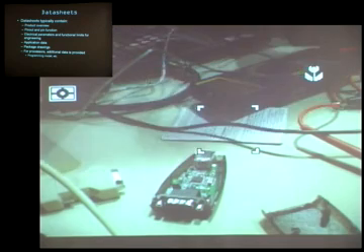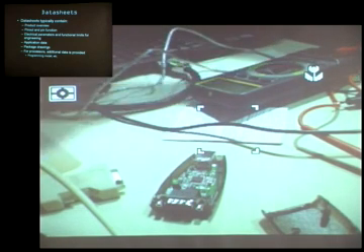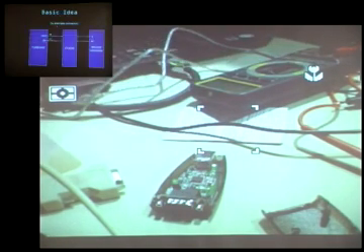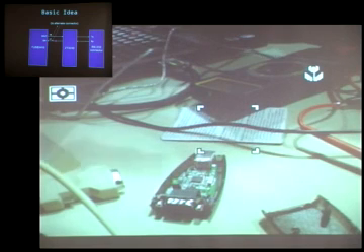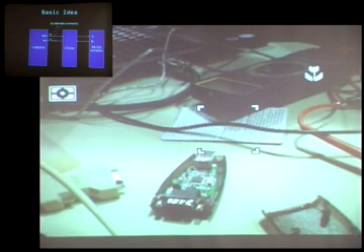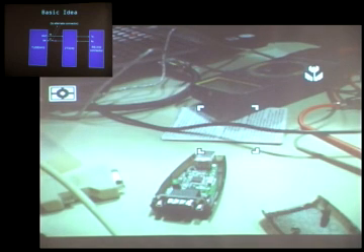So typically, you look at the data sheets to find those things, for example, product overview, pin function. I won't go into details given the short time. But the basic idea now is that we've got enough of a schematic to get working. We've got a TUSB3410. We've got the level converter that goes from the low-level voltage to the high-level voltage for RS-232 in the connector. I've identified pins 17 and 19 of the TUSB3410 as interesting signals.